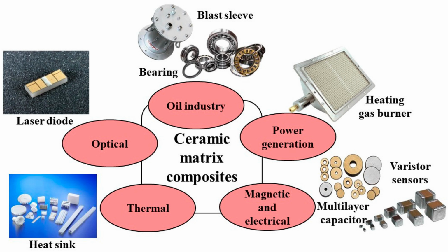Ceramic matrix composites. Ceramic matrix composites, CMCs, are produced by reinforcing ceramic matrices with ceramic fibers or particles to improve toughness and thermal shock resistance. These composites are increasingly used in aerospace turbines, hypersonic vehicles, and thermal protection systems because they maintain strength at temperatures beyond the limits of metallic alloys. Properties of ceramic materials.